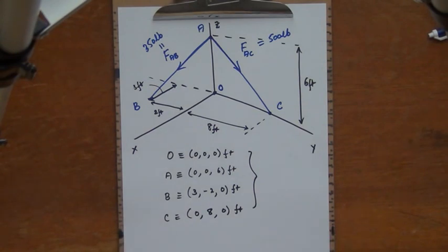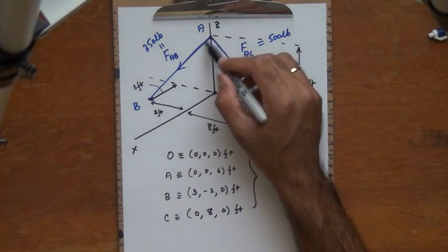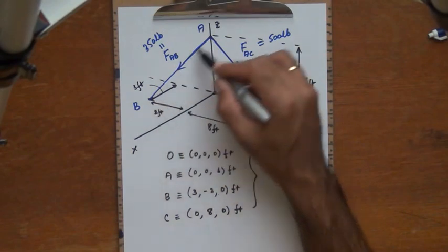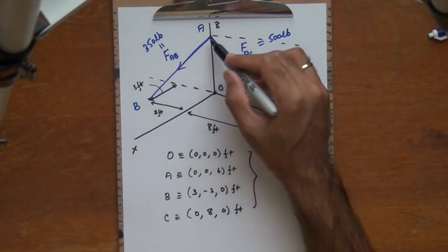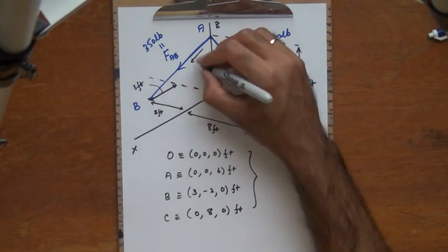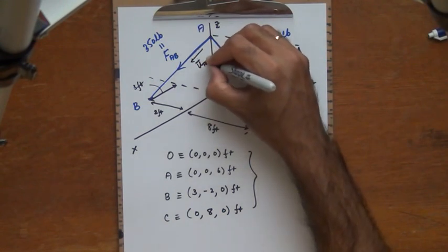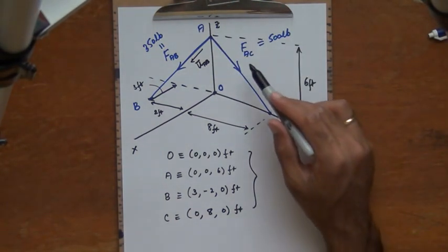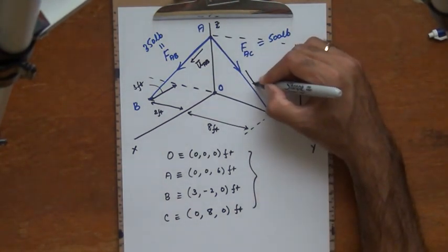And then the next step is to write each of the forces as a vector. Now you see that the force FAB is acting from point A to point B, which means the unit vector along its line of action is the same as that from point A to point B. So the unit vector here is UAB. And you see for the point A to C, the force FAC has a unit vector which is going to be UAC.